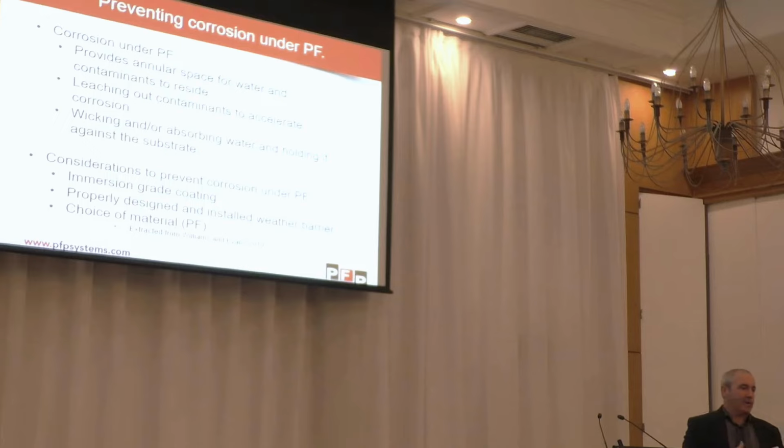On complex vessels, often the finish at penetrations or ports, etc., is one of the danger areas. So the finishing around those areas is quite important, to prevent the third movement, the wicking or absorption of water, because it'll find its way through and cause all manner of damage.